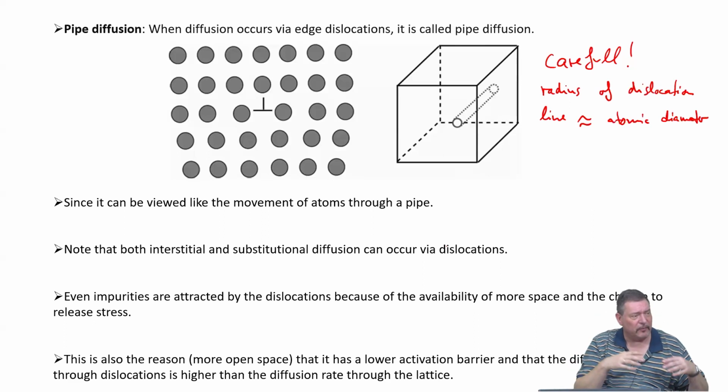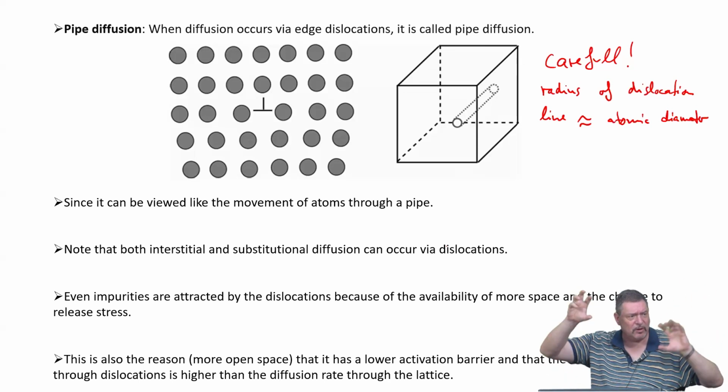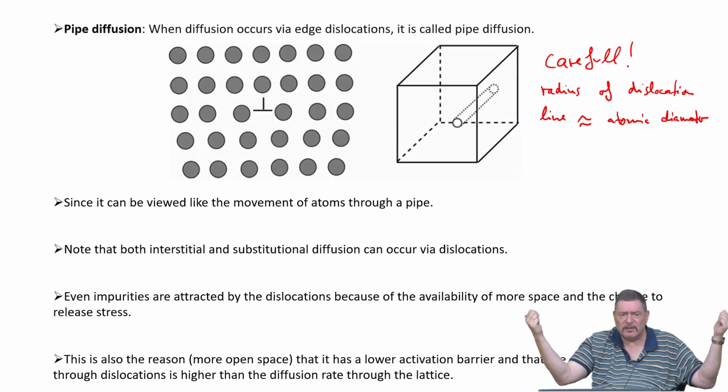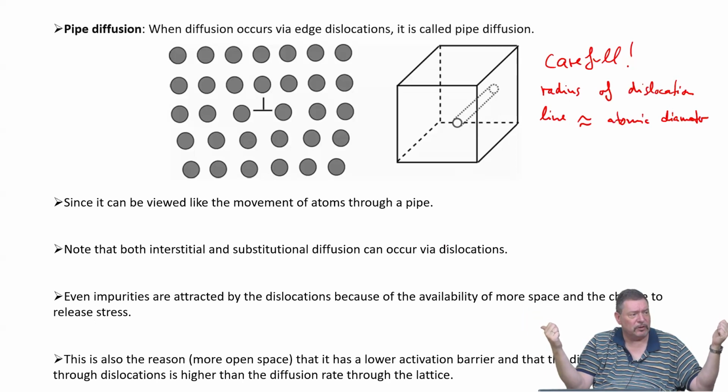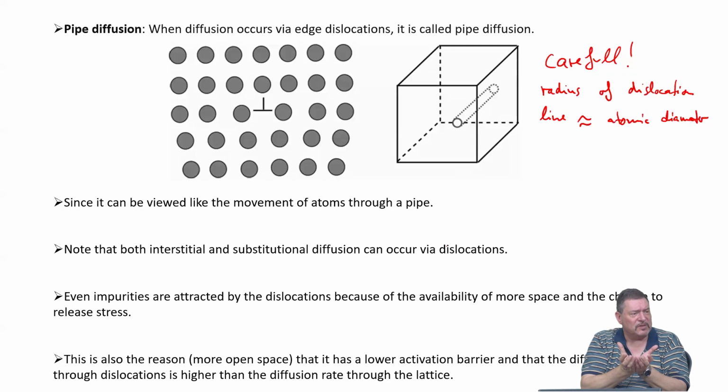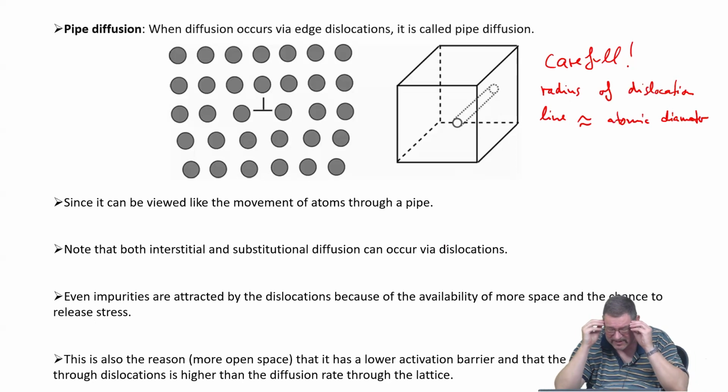So if we now think of the description of diffusion as being based on Brownian motion, on random jumps in all directions that are possible, it's not the case here, right? Because the forward jump or backward jump along the dislocation pipe will be easier than outside, because there is higher density, less available spaces for doing the diffusive jump. And this is causing so-called ballistic effects, because the configuration space of possible jumps is confined in a one-dimensional way. And then the mathematics again change a bit.